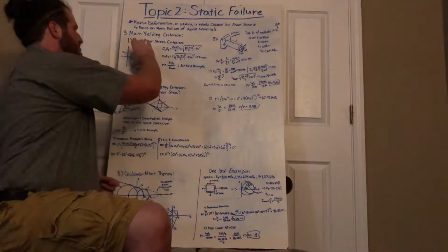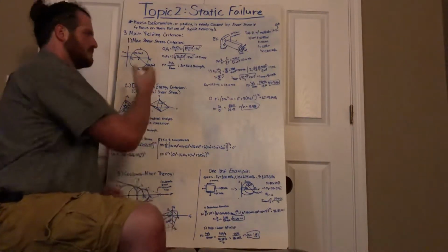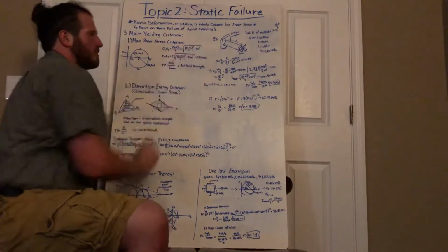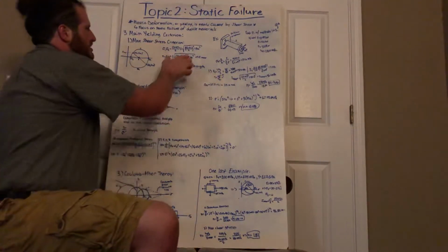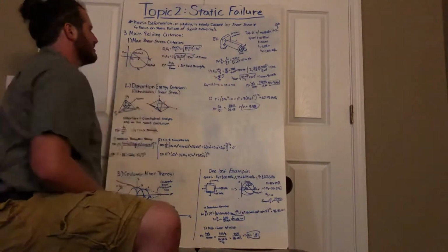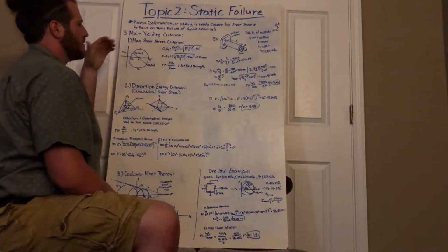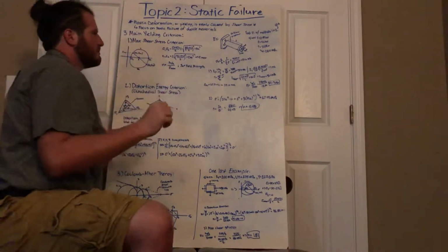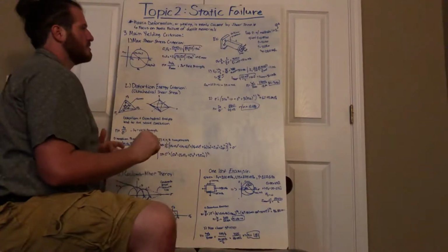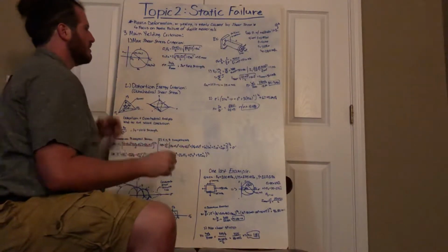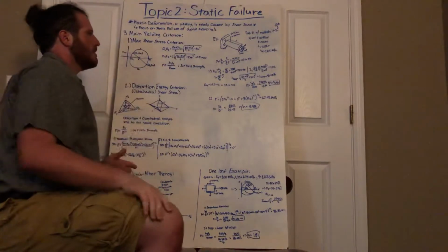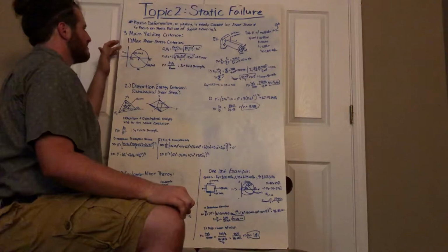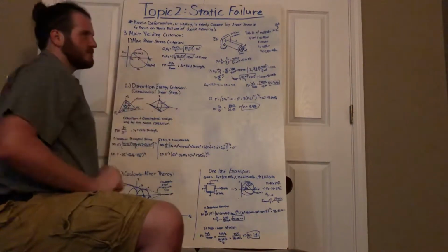But how do we get the principal shears? Well, there's another equation simply derived, which so happens to be the latter part of this equation. So once again, it'll be either plus or minus the square root of the entire thing of sigma x minus sigma y over 2 squared, plus tau xy squared, or the shear of the xy plane squared. Now, this will lead to our sigma max. Our sigma max is important for determining our max shear stress criterion.